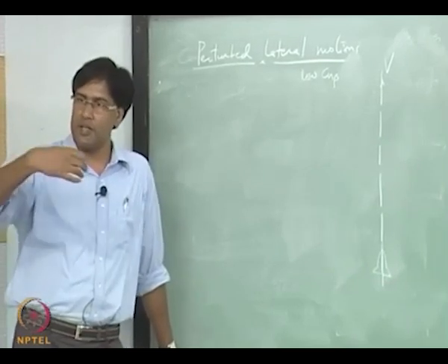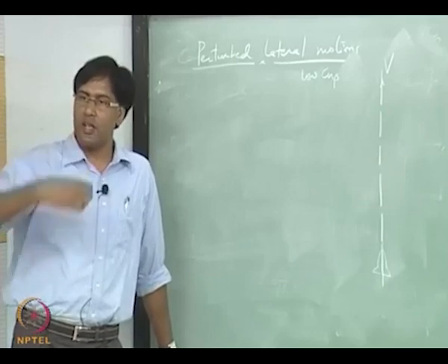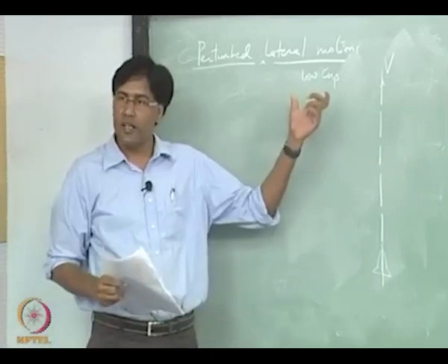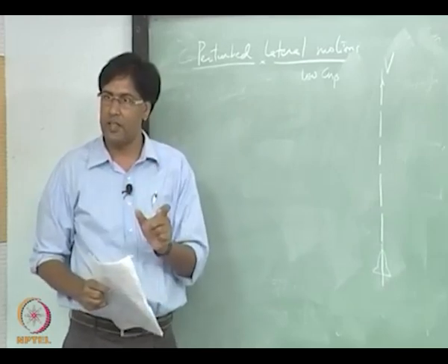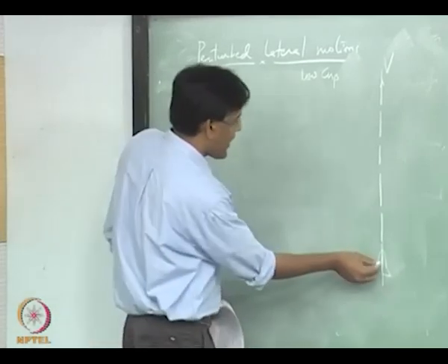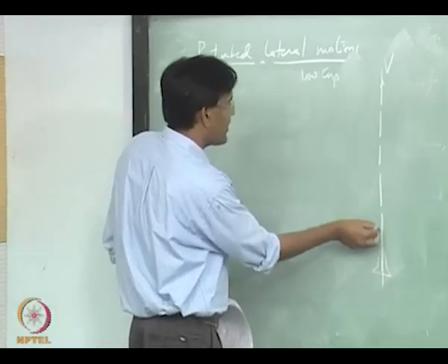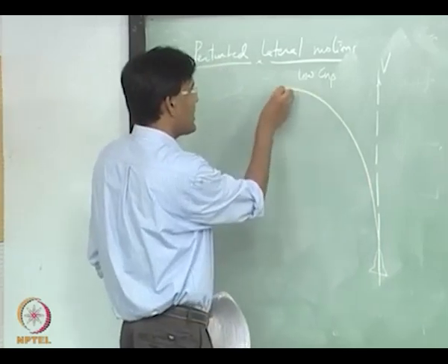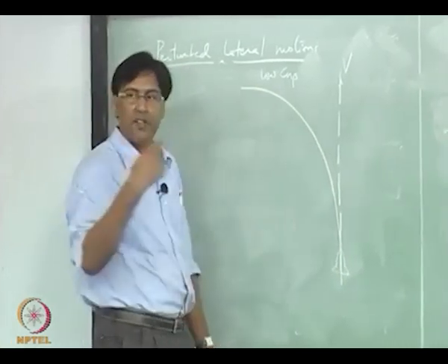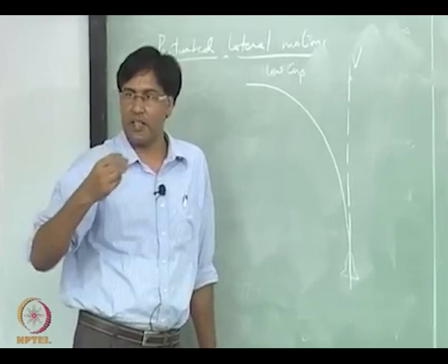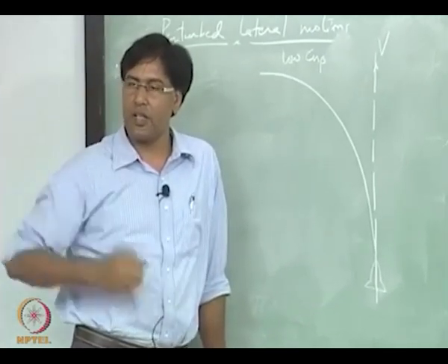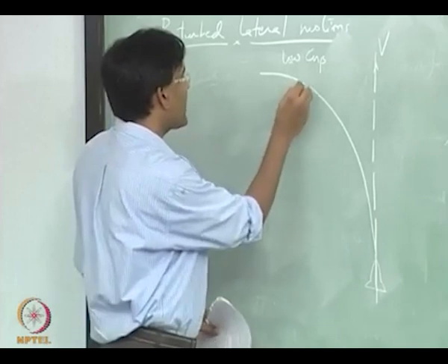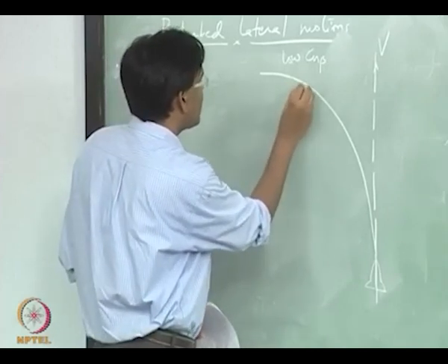A perturbation is introduced, and the Cn beta will not be enough to kill that delta beta. So the aircraft will start going on a curved path like this, and the beta will keep on increasing. That delta beta will keep on growing, and finally your aircraft will be flying like this.